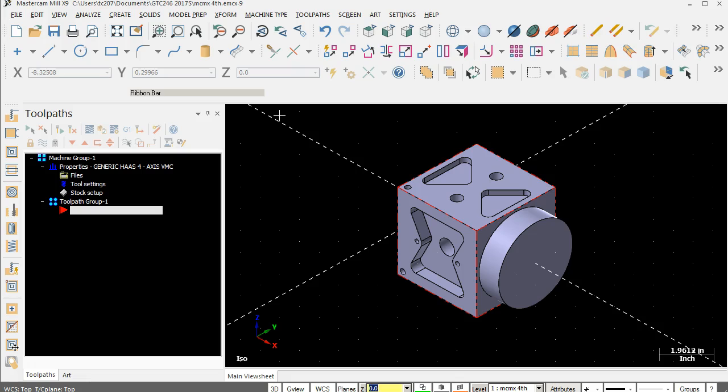You're dropping down 4 inches. That means every time I do a tool change, I may have to write in a manual operation that says go to this safe tool change position before you do the tool change, right, before you pick up the next operation. Right, so those are all considerations that are going to play into this